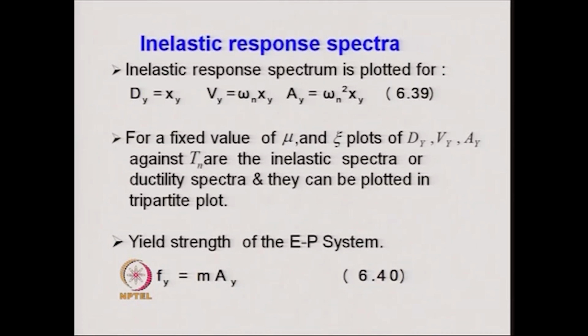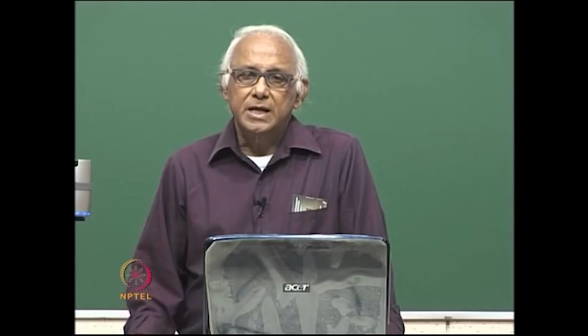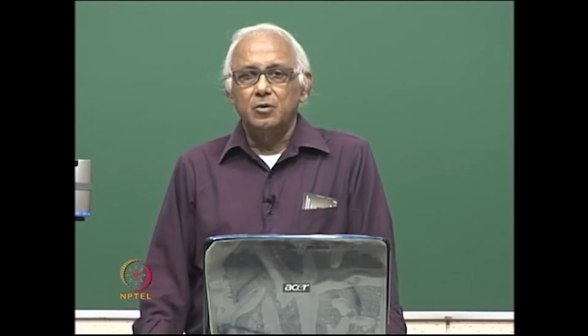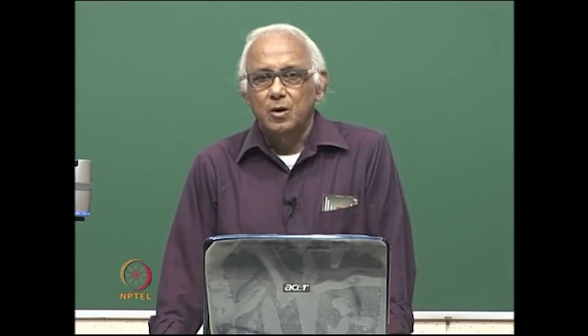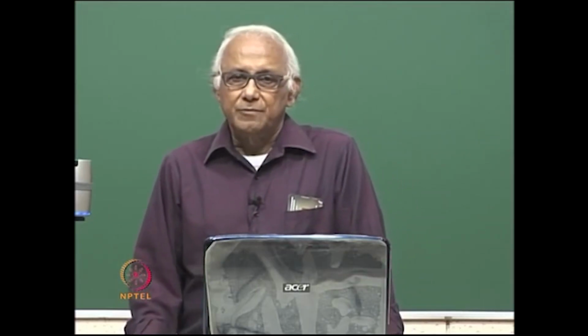Now, once we get that, from f bar y one can find the value of f y, because f bar y is equal to f y divided by f 0, where f 0 is the strength corresponding to the purely elastic system. In other words, for the same earthquake we find an elastic response, and from that elastic response one can get the value of f 0.